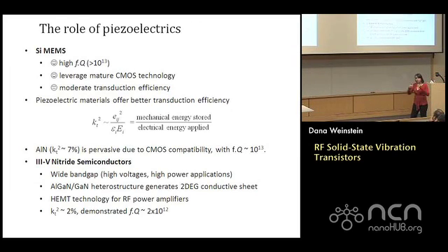Okay. So in terms of silicon CMOS resonators, this is where we stand, and it's very promising first results, and we're going to keep pursuing this and push into the application space, because the idea is I've got these devices I can plop into layout, send off to the foundry, and get back as a complete process, no post processing or packaging. So silicon gives us high quality factor, it gives us CMOS integration, and we can leverage the mature CMOS technology.